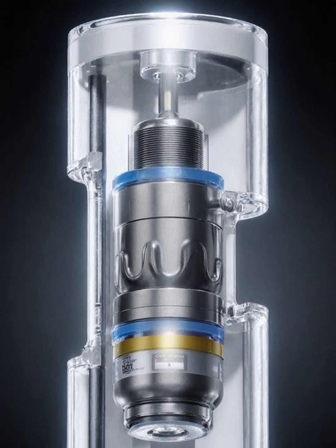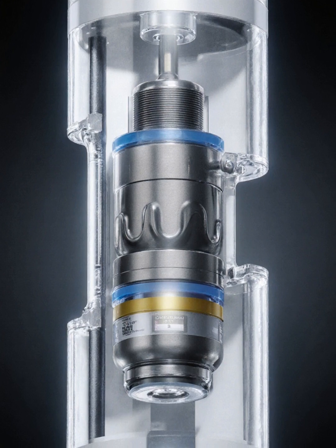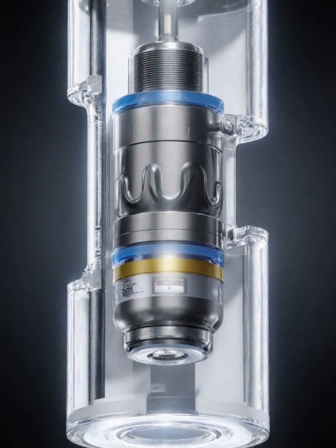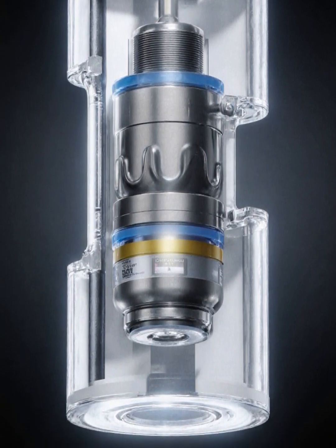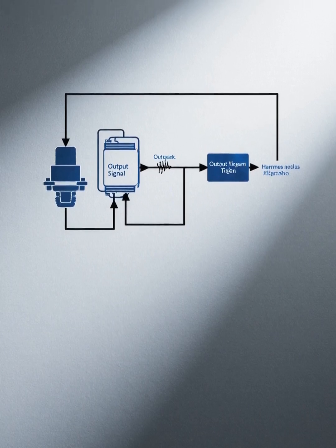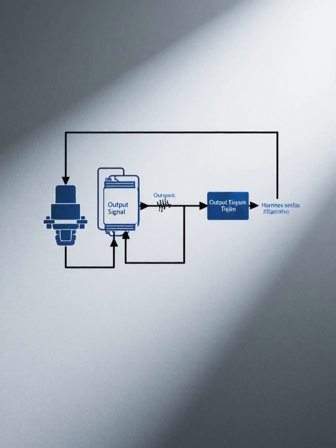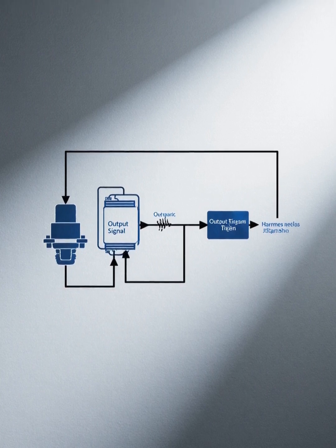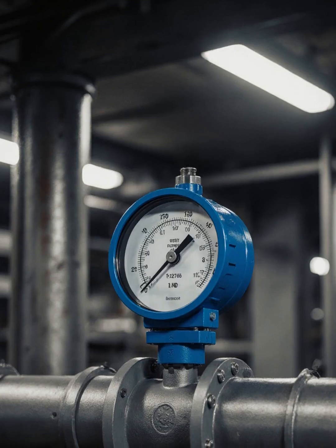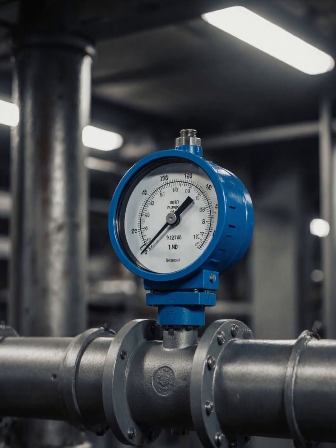Vortex flow meter. A vortex flow meter has the following components: a flow sensor, operable to sense pressure variations due to vortex shedding of a fluid in a passage, and to convert the pressure variations to a flow sensor signal in the form of an electrical signal, and a signal processor operable to receive the flow sensor signal and to generate an output signal corresponding to the pressure variations due to vortex shedding of the fluid in the passage.